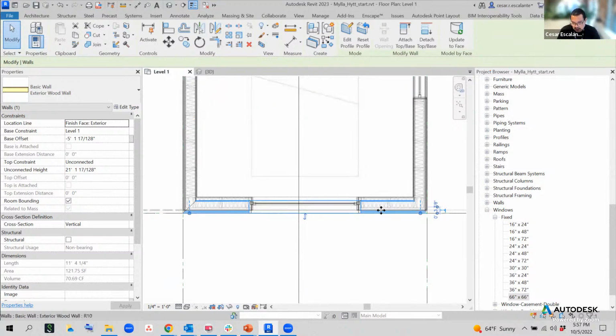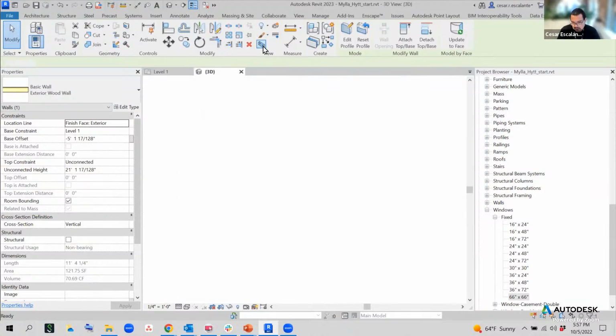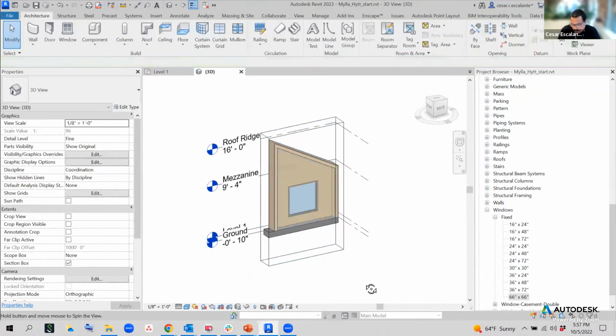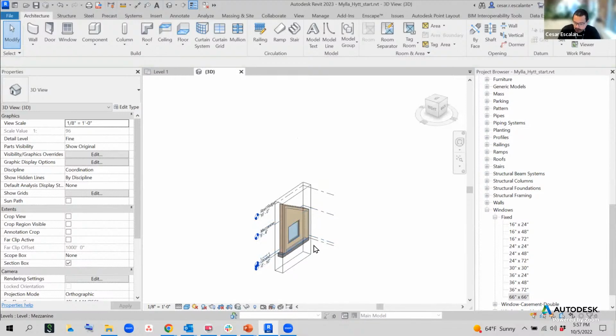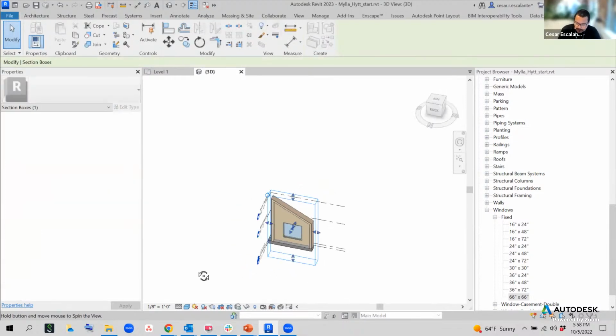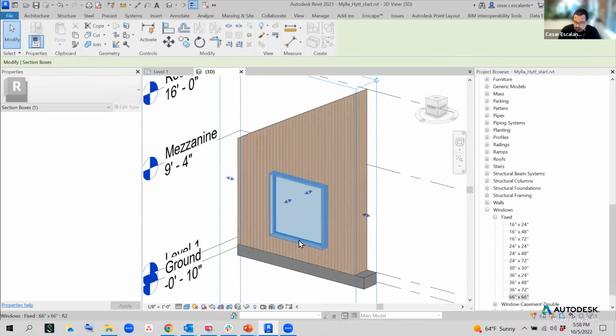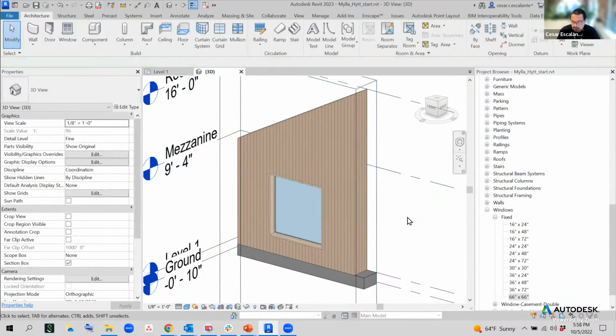So select it, click this, and when you switch to 3D, you have this isolated object in a bounded box that is, I think, 1 foot away from the geometry. And you have a way to understand its unique properties in 3D. It's used a lot just for visual check that what you're doing in plan is making sense in 3D.